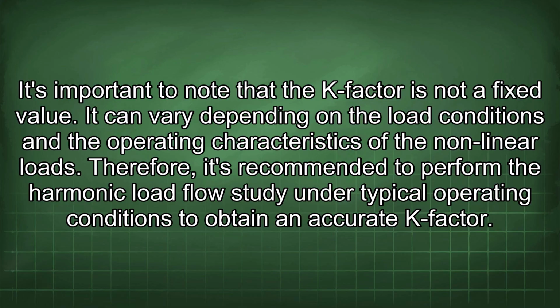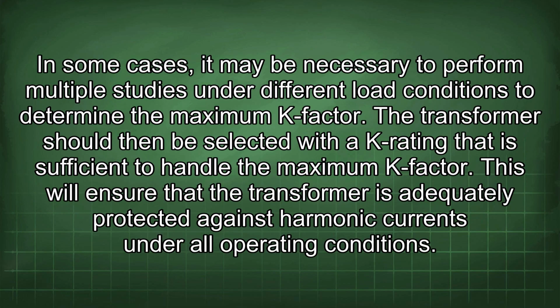It's important to note that the K-factor is not a fixed value. It can vary depending on the load conditions and the operating characteristics of the nonlinear loads. Therefore, it's recommended to perform the harmonic load flow study under typical operating conditions to obtain an accurate K-factor. In some cases, it may be necessary to perform multiple studies under different load conditions to determine the maximum K-factor. The transformer should then be selected with a K rating that is sufficient to handle the maximum K-factor. This will ensure that the transformer is adequately protected against harmonic currents under all operating conditions.